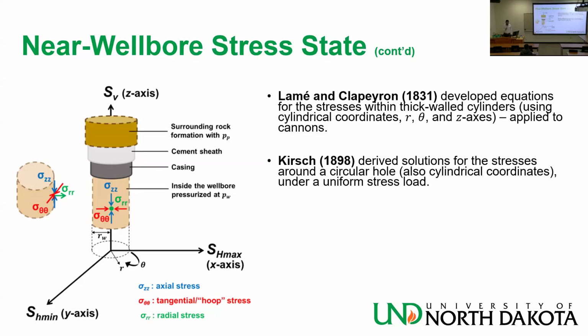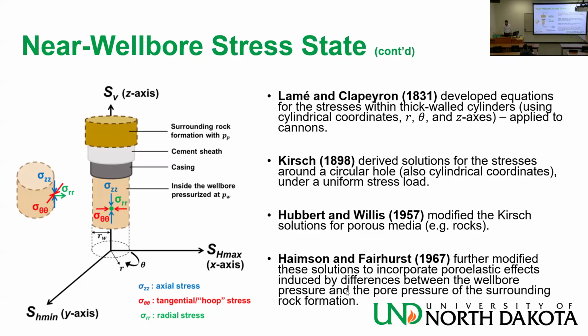Anyway, I want you to know the configuration of the stress. The radial stress is in the direction of a radius going out to the circumference. If you extend that, that's the radial stress. Orthogonal to it, we get the tangential stress, and the z stress along the direction of the well. Those directions are important because they dictate fracture initiation.